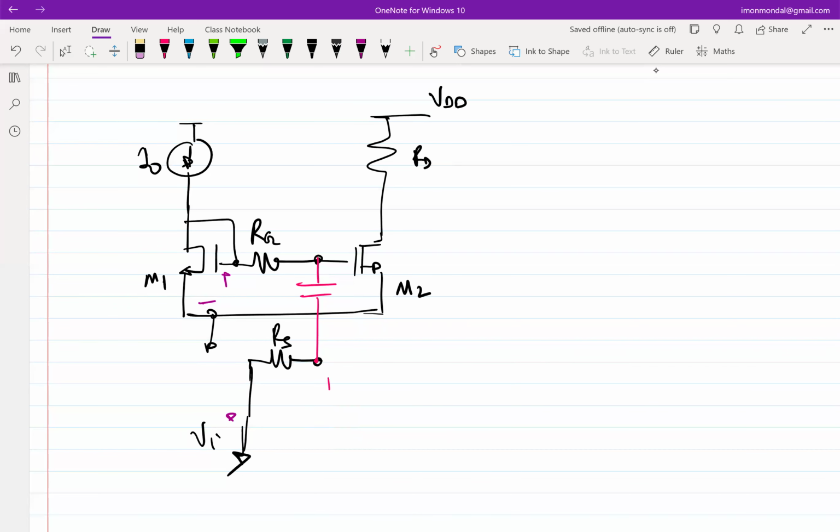If I put a capacitor, at least now we see that, quiescent wise, there is absolutely no change, so for quiescent operation you don't even have to bother to analyze. Let's analyze what's going to happen to the incremental network. He said RG, that's why I put RG. So I'll remove RG.